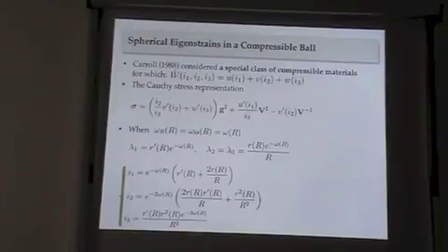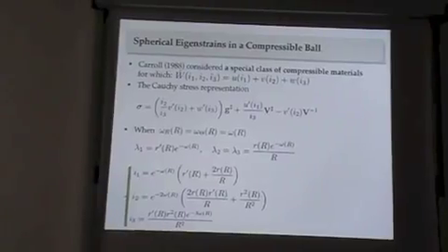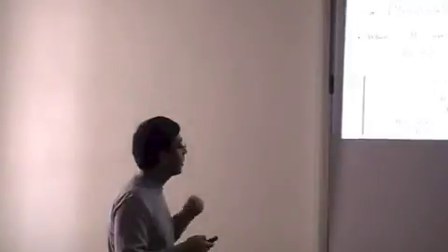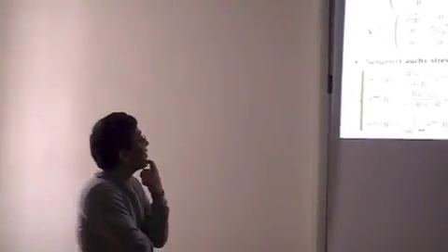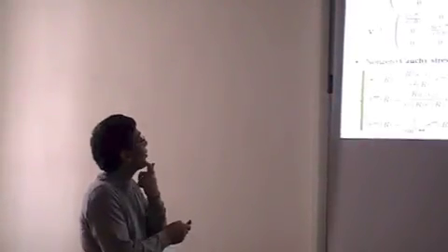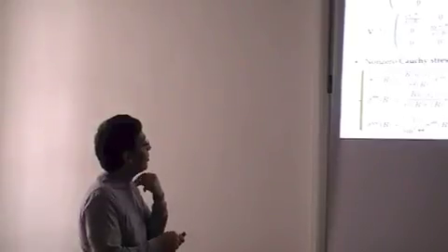Now, for compressible, I'm going to assume that these two are equal, and I would have my principal stretches, I1, I2, I3. My goal is to prove a proposition that we just did for this subset of compressible solids, in particular what those two guys did numerically. Okay, so this V sharp inverse looks like this.